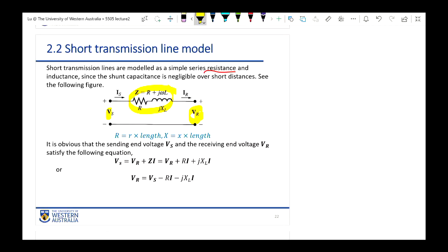We just use the line current multiplied by the impedance of the cable to calculate the total voltage drop during the transmission. The total supplied voltage, Vs, should be the summation of the voltage drop across the transmission plus the voltage received by the receiver.